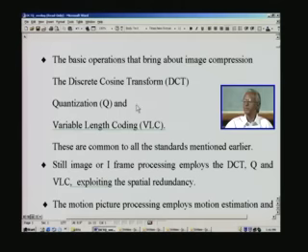That DCTQ output is parallel, say for example a 9-bit value, and that will be the input for the variable length coding, and out comes just a single-bit stream. This bit stream is a compressed stream, and compared to the original input you will have a factor of 10 to 50 compression depending upon the algorithm and techniques we adopt.